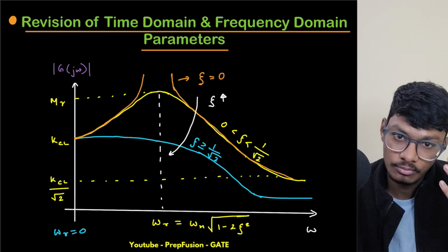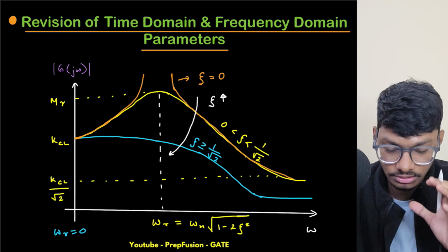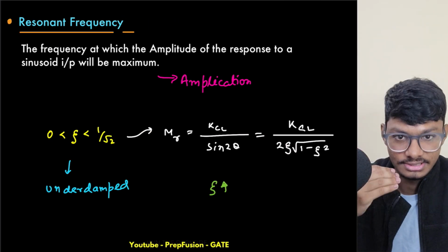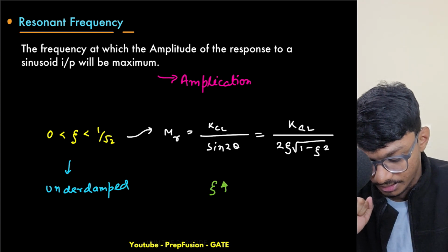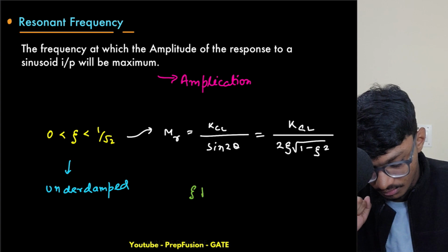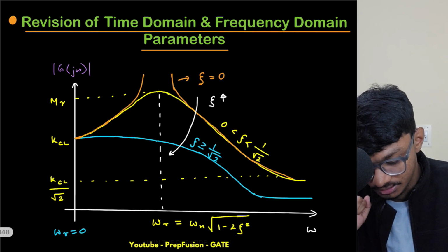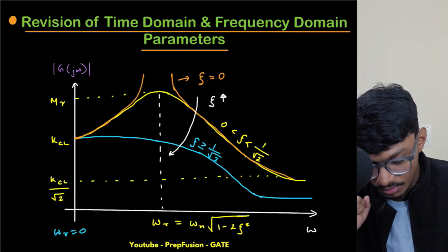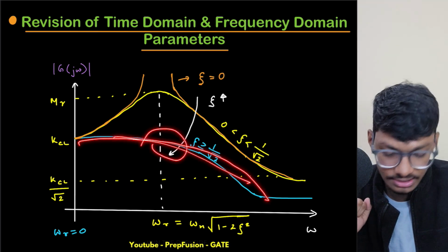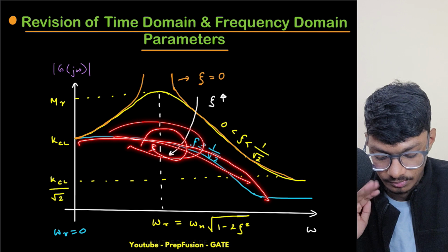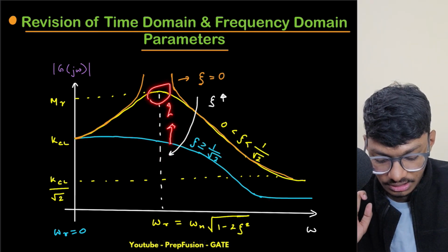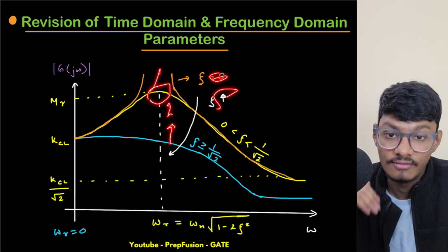Here, we have already plotted that in our graph plots in our previous chapters. If I keep on increasing, sorry, I meant to decrease zeta, because what you can observe here is that here my zeta is maximum where my peak is minimum. Then I slowly go reducing zeta, my peak increases, then I go to 0, my peak further increases.